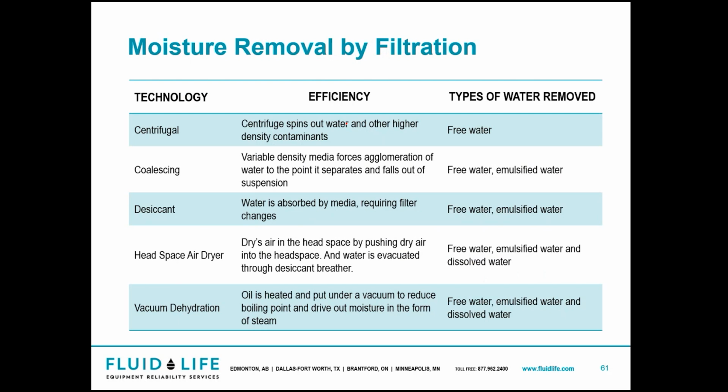So again, water can come from free sources, dissolved, and emulsified. Again, if it's emulsified, it's going to look cloudy. Filter your oil. Help get out the water. Help get out the contaminants. Make sure that we are storing our lubricant properly. All these factors are going to be a huge first step before sampling, before anything. Contamination control. As soon as that barrel of oil is received on site, making sure that we have all the processes in place is going to be a huge benefit.